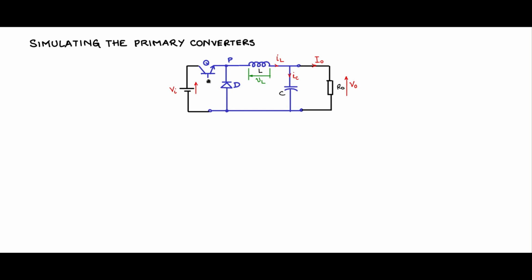So what I have done here is that I am passing it through a PWM generator block during simulation and giving a voltage which is proportional to duty cycle. If I want lower duty cycle, I will decrease the voltage, higher duty cycle, I will increase the voltage, and this will be compared with a triangle waveform to generate the PWM, and these signals will turn on this BJT.